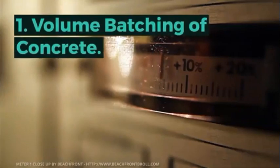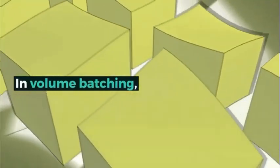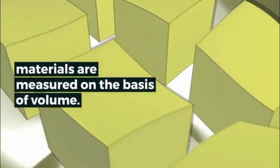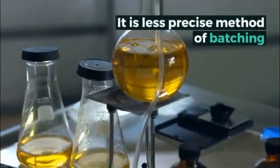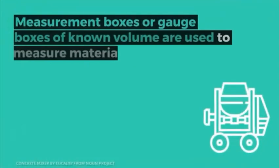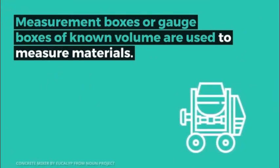Volume batching of concrete. In volume batching, materials are measured on the basis of volume. It is a less precise method of batching. Measurement boxes, or gauge boxes, of known volume are used to measure materials.